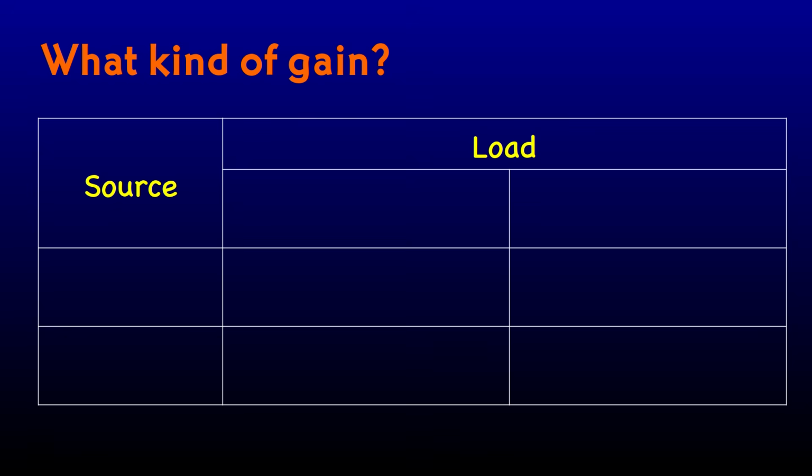If a signal is a voltage, we generally want the output impedance of the source to be as low as possible. More to the point, we want the input impedance of the load to be as high as possible. That's because if they don't match in that way, we'll lose a lot of our signal, because the source and the load will form a voltage divider. We often use the rule of thumb of making the input impedance of an amplifier at least 10 times the output impedance of its source. Sometimes in precision circuits, we either want to make it much higher than that, or introduce extra complexity to compensate for the loss.